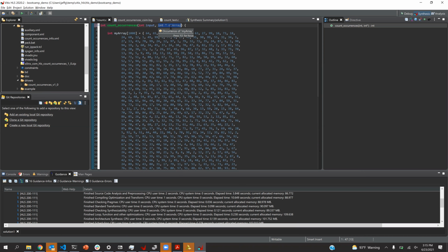Well, it becomes its own DMA, essentially. It builds the hardware that can talk to the bus and get data out of memory. Okay, so you wouldn't need a DMA. You could do other things. You could make a streaming thing. Maybe you have some circuit that just provides this whole array in, not through a memory access bus, but through like a FIFO, or just like a stream of data coming in one cycle after the next.